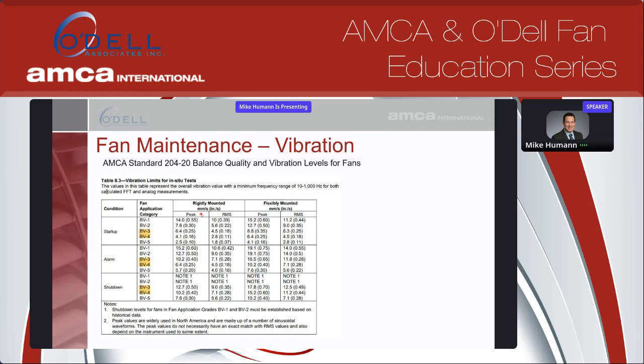Also, make sure you know how you're measuring it. Are you measuring it as a peak value, or are you measuring it as an RMS value? Because you see these numbers vary differently. So you just want to make sure you're comparing it to the right column based upon how you're actually measuring that vibration level.